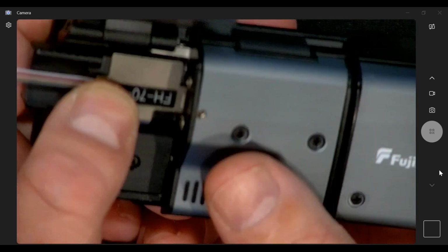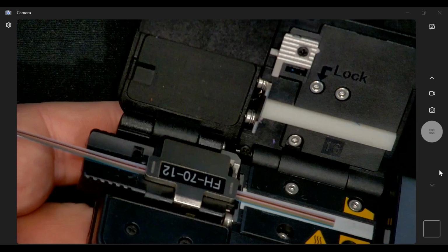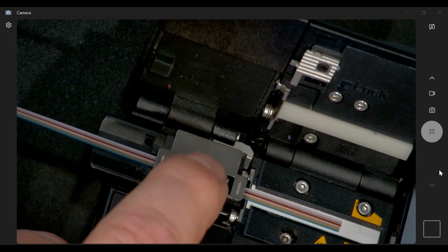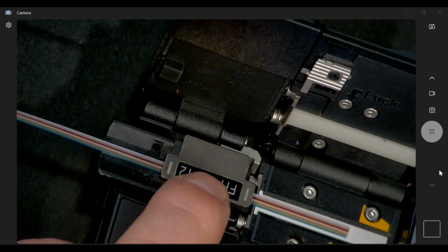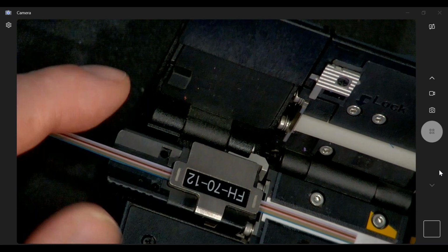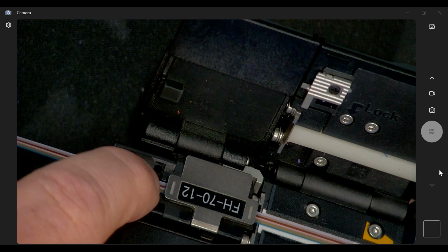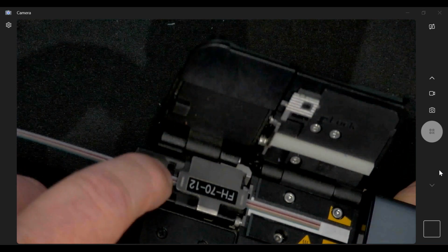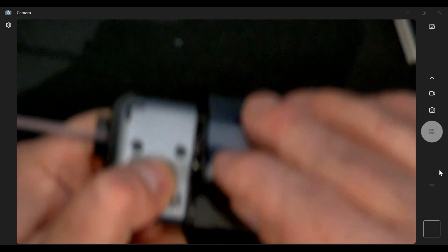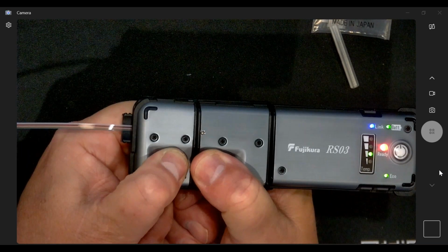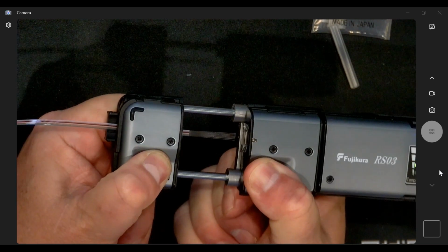The thing that you have to remember with a hot jacket stripper is that there are some friction points within the hot jacket stripper. Of course, you've got the ribbon being held by the fiber holder cover itself with a rubber boot on top of the lid. You have this small foot that will come down and pinch and press the ribbon into the fiber holder in the hot jacket stripper itself. As I go to hold this, the general rule of thumb is that I want to hold this with firm pressure. When it turns from red to green, open it up.